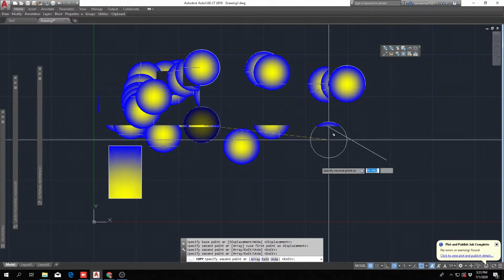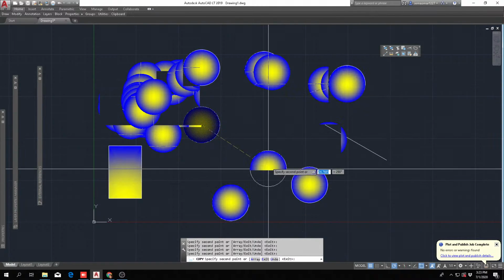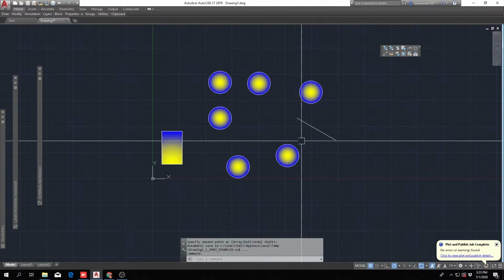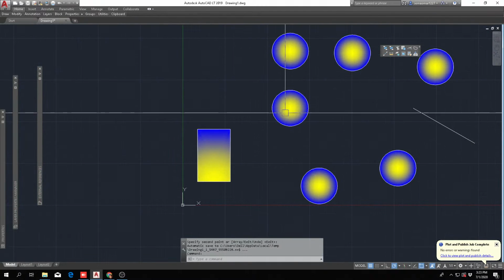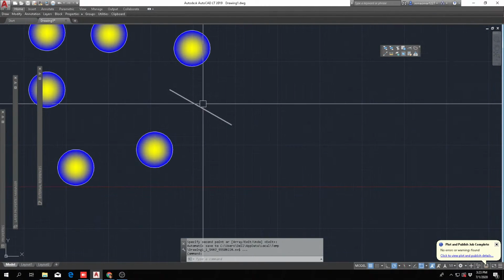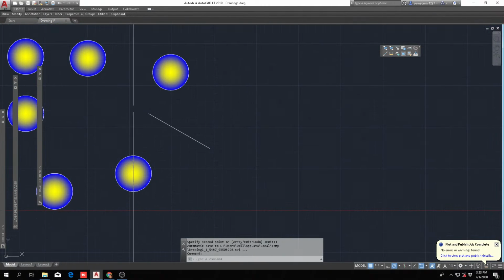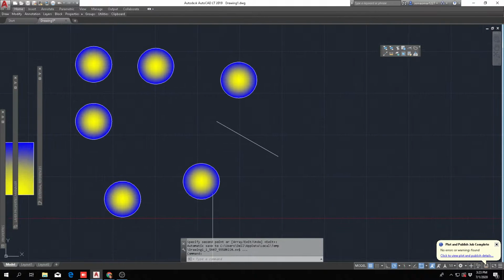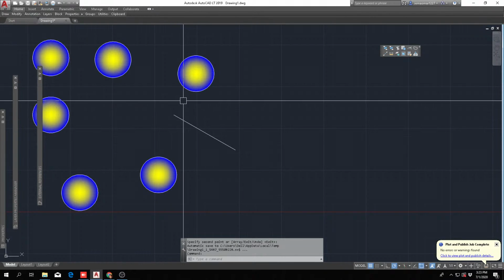And you see right there. Now I know okay, there. So it just clicks on wherever you want them. So let's do it with a line, so there's not too much of, because for some reason the hatch is just the graphics of the AutoCAD, it just messes it up whenever you move the hatch.